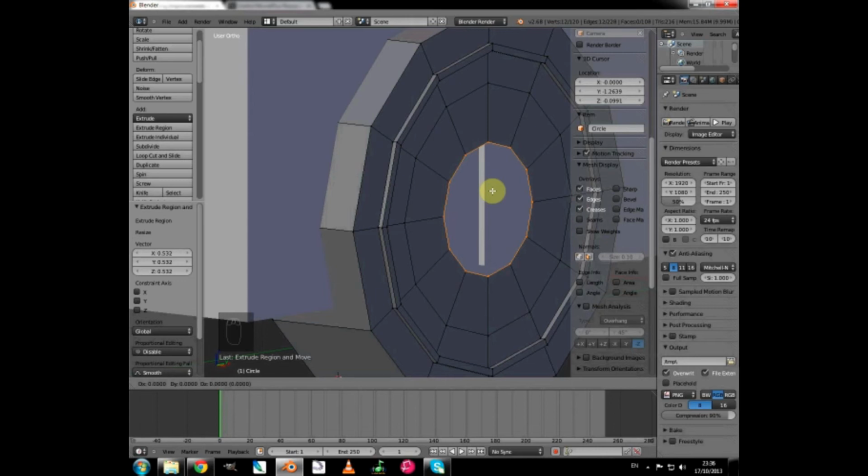the right mouse button, and what we have there, we have this loop sitting on top of the previous loop, so we've basically got a duplicate loop connected to the loop underneath, and that's not a good thing to have, but I'm just warning you so you don't go off and do something else. We're going to merge that loop in the center, and we can use the toolbar.